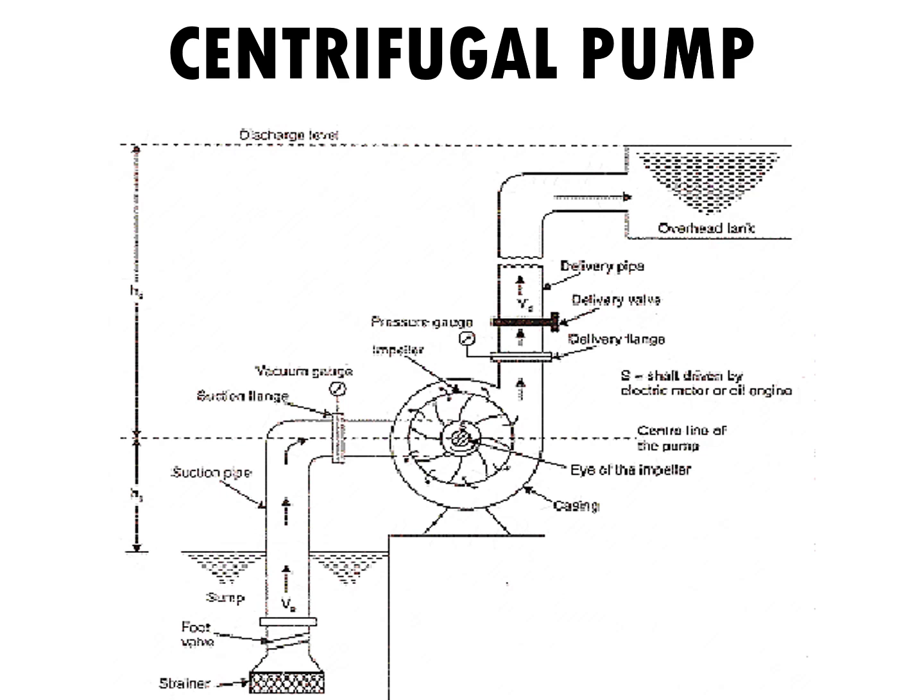Now below, on the suction side, first you have a strainer to filter the things, and then a foot valve, and water is taken up through the suction pipe and it reaches the scroll casing. From there, a pressure gauge or a vacuum gauge is fitted to measure the pressure, and then water is forced into the impeller and it rotates. Due to the centrifugal action, the pressure of the water inside gets increased, and this pressurized water is then taken to the delivery side.